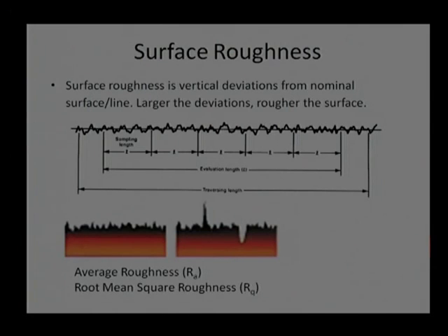After driving at low speed for some time, we change the oil. That means all the large size asperities are broken or torn away from the surface, they get mixed with the oil, and we replace that oil and get a good surface for a longer life. After that, we can speed up the vehicle and drive at the higher speed.